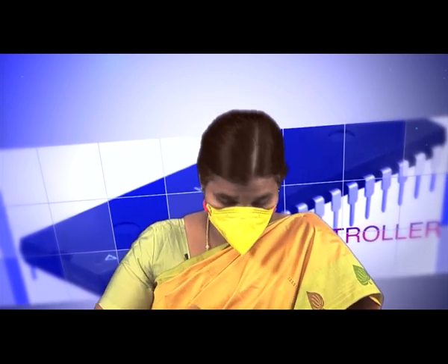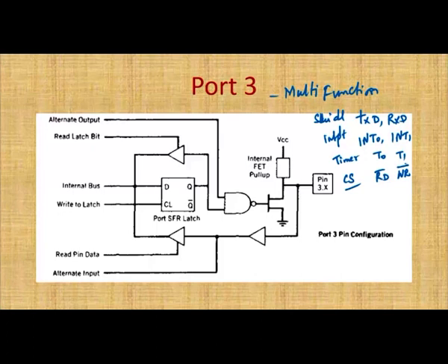So, for the input operation, whatever I am writing as the signal here should come over the pin, right. Suppose I have taken the value of 0 here, I am expecting 0 on the pin. We will check whether the path allows the 0 to the pin. Because of the D latch, whatever you are giving will come out here, right.